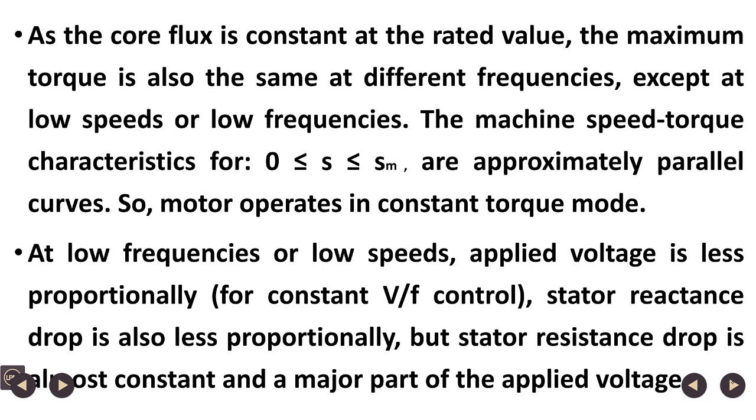And impedance drop has 2 parts, resistance drop and reactance drop. At low frequencies, voltage is proportionally less, reactance is proportionally less, but resistance is almost constant. So, because applied voltage is very small, the stator resistance drop is a major part of the applied voltage.